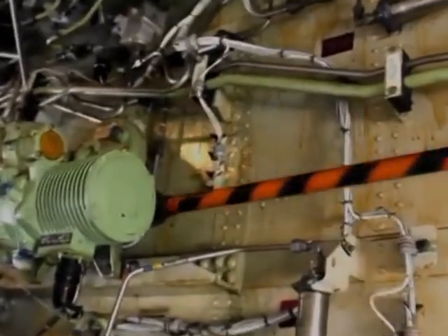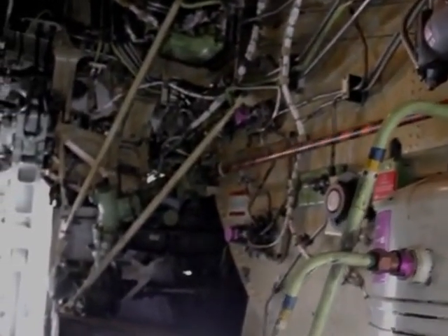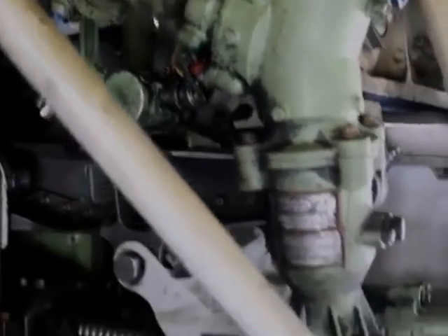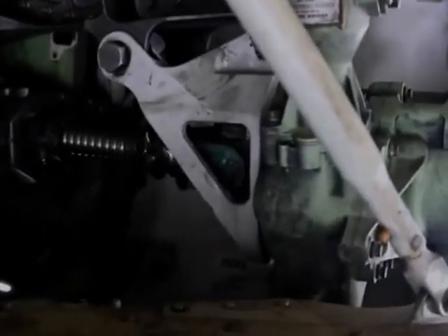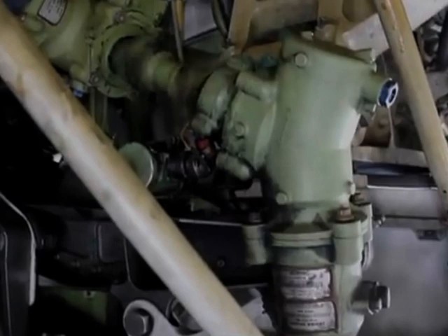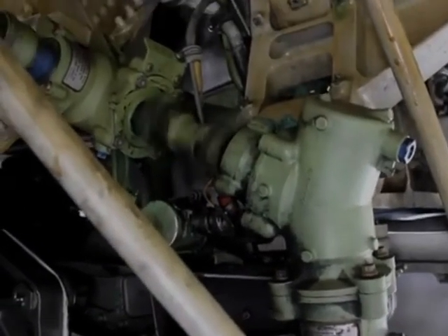As said before, the normal flaps for landing are either flaps 30 or flaps 40. In order to prevent excessive load, stress and damage on the trailing edge flaps, mostly when we come for the landing, because sometimes the speed during the landing increases, we have a load relief system on the trailing edge flaps.